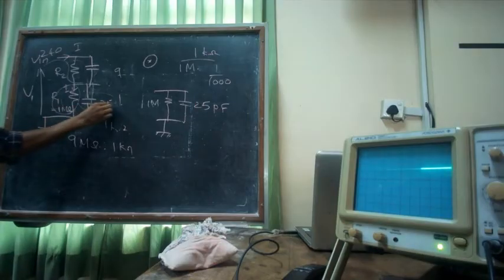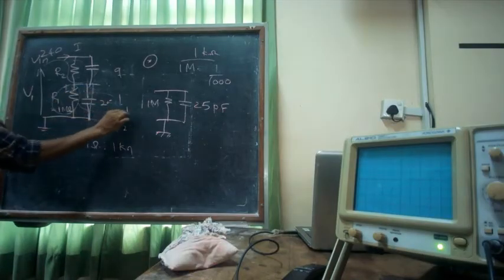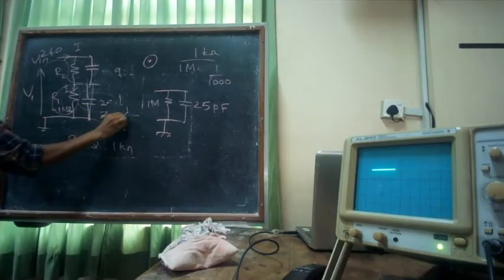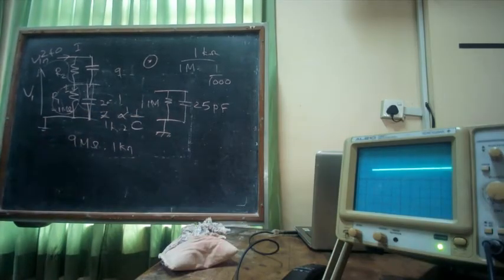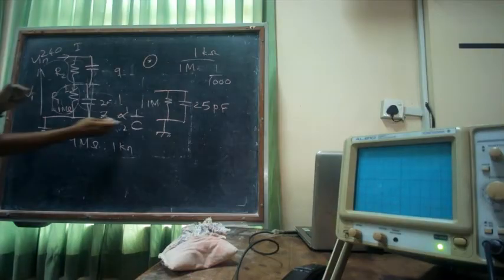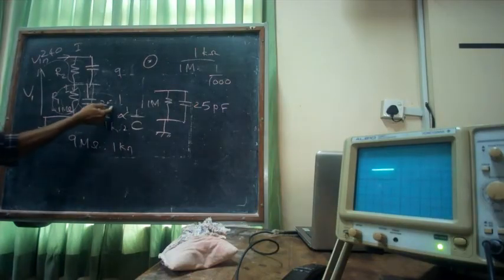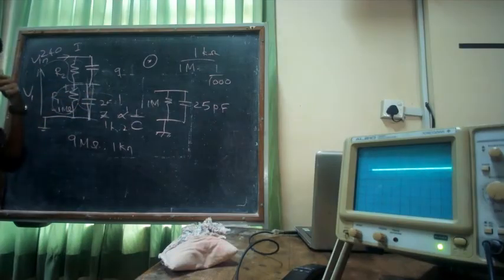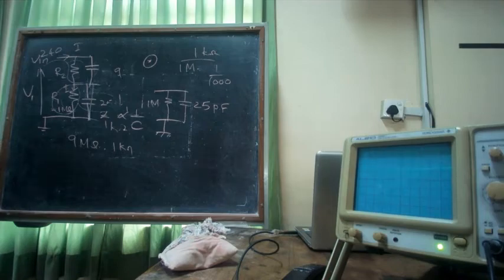So if this is picofarad, typically the impedance, which we call Z, is proportional to 1 over capacitance. The higher the capacitance at a particular given frequency, the lower the impedance, right? So therefore, if this is 25, I need to have 9 times less capacitance in order to achieve the same effect, right?